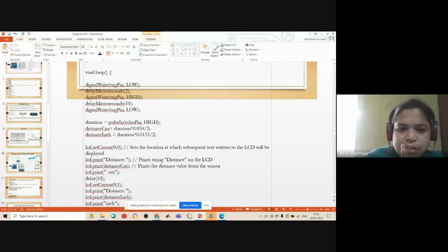Over that period of time it is in the on condition. Once it is low, it waits for an echo from the receiver, so that acts as an input pin. The pulseIn on the echo pin automatically goes high. So you know the distance in centimeters is calculated with this 0.034. Anyone have a guess what it is?